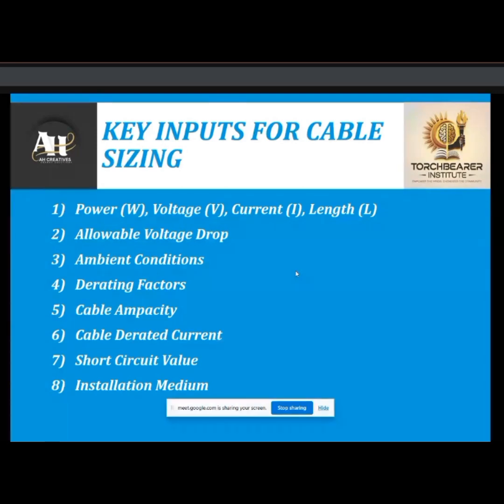We are laying our cable in the direct buried case. Direct buried, basically, means we don't use any medium between the ground and cables. And the other one is the duct bank case, where we install our cables in ducts. So the ambient condition is very important, and we have to analyze our cable sizing on that basis.